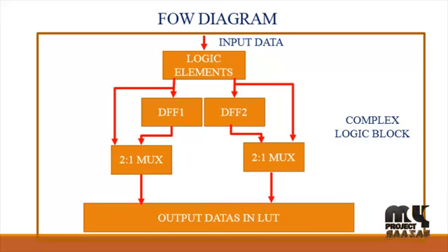And next, the logic element consists of a multiplexer. Here a 4:1 multiplexer is used, and multiplexing is the generic term used to describe the operation of sending one or more analog or digital signals over a common transmission line at different times or speeds. The device we use to do just that is called a multiplexer, or mux. It is a combinational logic circuit designed to switch one of several input lines through to a single common output line by the application of a control signal.